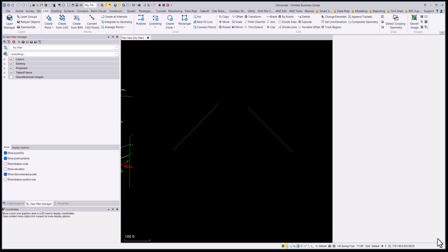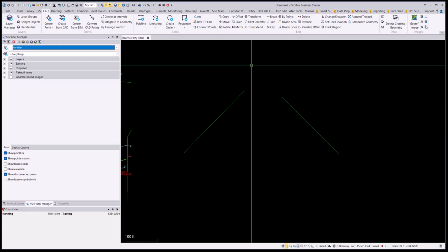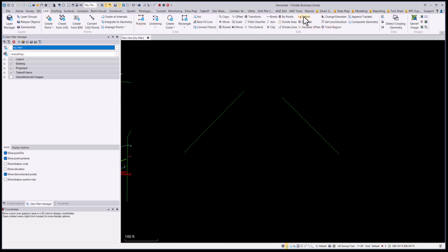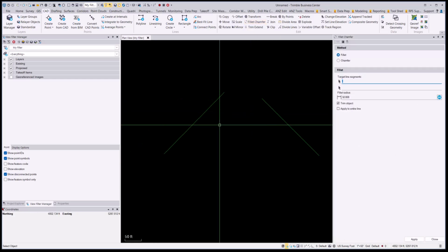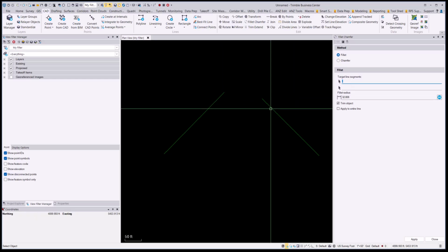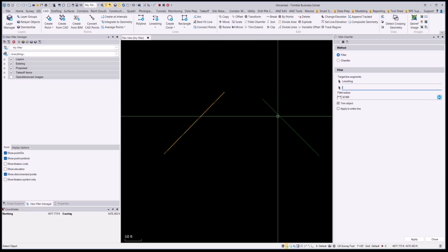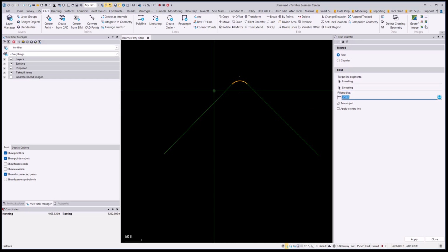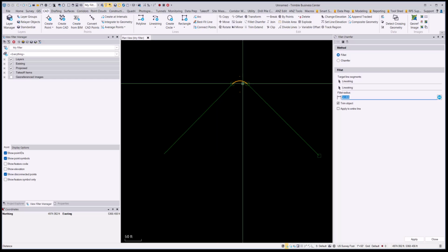Okay. There is another command that I use a lot, under the CAD tab, under this edit group, and that's the fillet chamfer. Now the fillet chamfer you can use by picking two lines, and then you can tell it to make a corner, make it a radius corner. So if I use this and I pick here and I pick here, you can see it extends the two and puts in a 32.808. That's just the default radius. Well, you can put the radius of 0.